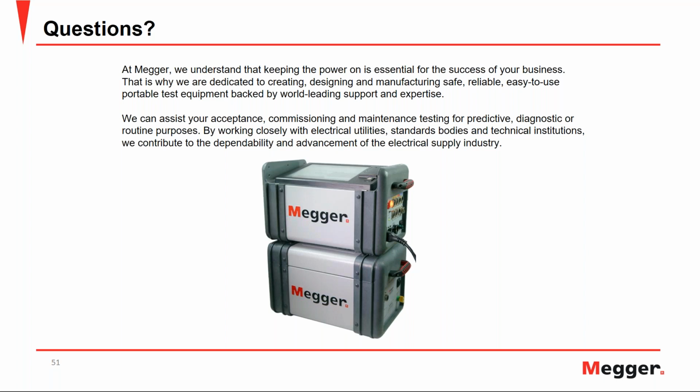Thank you, Dinesh. Charles, can you get into more detail about how the equipment determines VDF in the tests and if it calculates it when we are doing this frequency sweep? So the VDF is done at the 60 hertz, and basically the voltage dependence factor is the same as total harmonic distortion, widely talked about in power electronics.